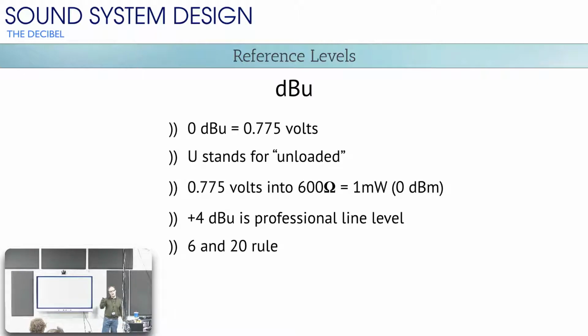So we go really high input impedance, and that means we could take the output of something and split it lots of ways, right? You can do Y cables, we can do mults and patch bays, and we can take that signal and split it as many ways as we want, and we don't usually lose a whole lot because that high input impedance allows for that energy to really spray right into the next thing. So even if it drops a little bit, it still comes in pretty well.